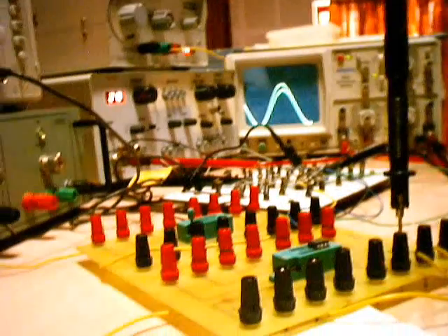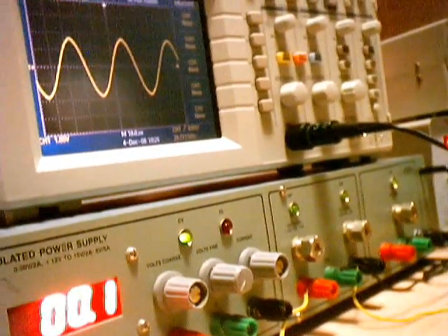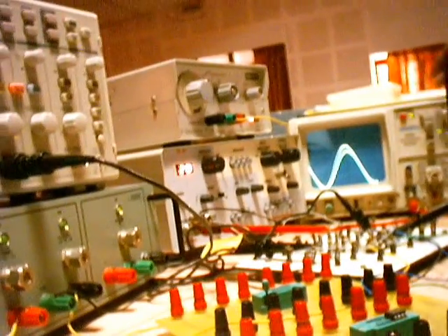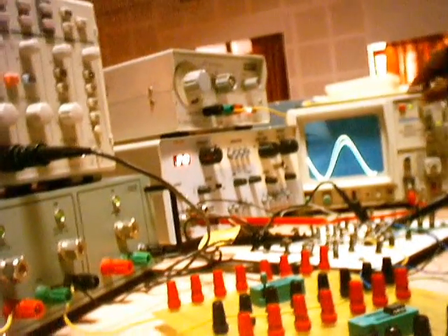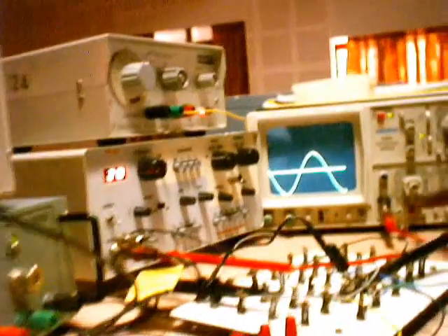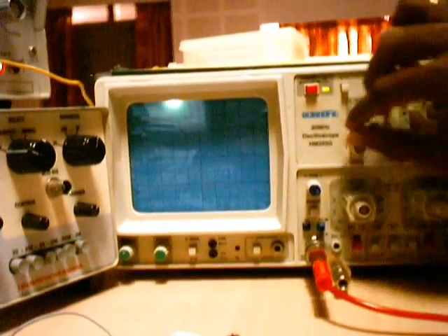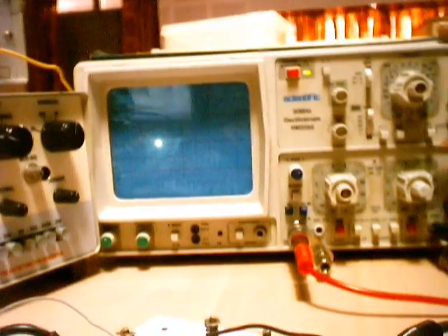You can continue with this setup. Now we need to find the cutoff frequency. We verified the passband gain for this high pass filter, which is designed for a cutoff frequency of 5 kilohertz. As we did for the low pass filter, let us again try to find the Lissajous figure of this one. For doing that, let us identify the grounds and have a dot at the center. So let me take the dot to the center.